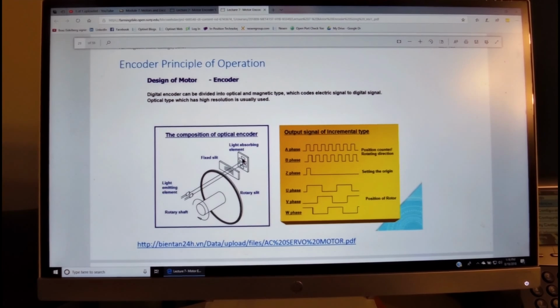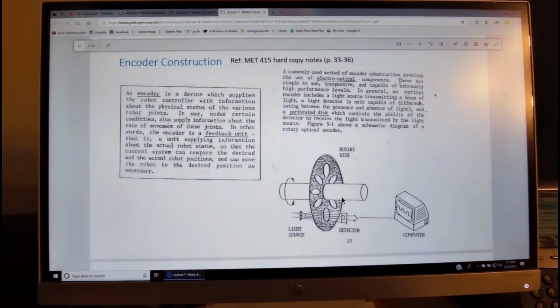So we see over here 3 of them, and then another 3 which are redundant in order to provide reliable counting. Similarly, we have the possibility of using these devices to commutate the servo amplifier in order to provide the currents at the right timing to the coils.